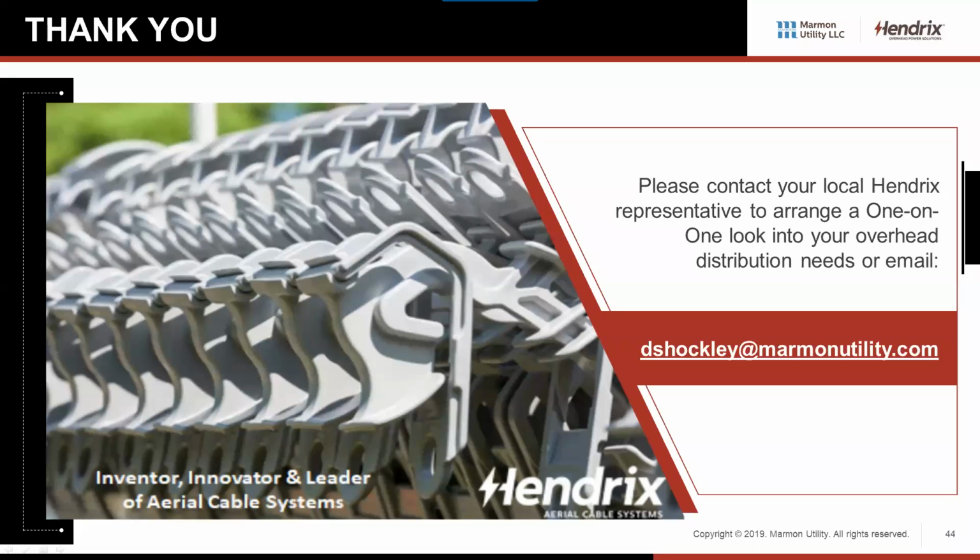It's incredibly difficult for moisture to get inside the covering of the conductor. If it does, it's all aluminum conductor. It's really not going to hurt anything. There's no steel component to it to deteriorate or corrode. But it's also compact, so there's really no airspace in there for moisture to get. With underground, you're kind of taking like a wet sponge and you're putting it on the cable and you're almost forcing water into it. And obviously, because it's insulated cable and you've got a ground shield on the outside, it's always trying to work its way through that insulation, and that'll cause failure.